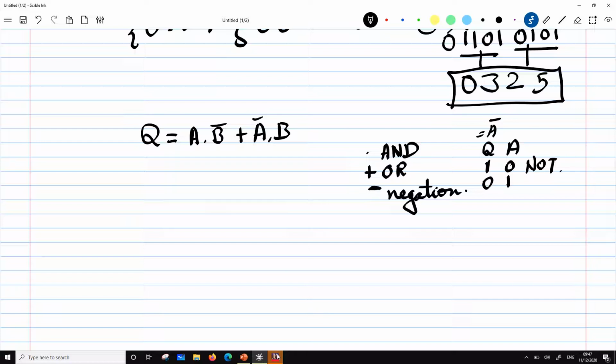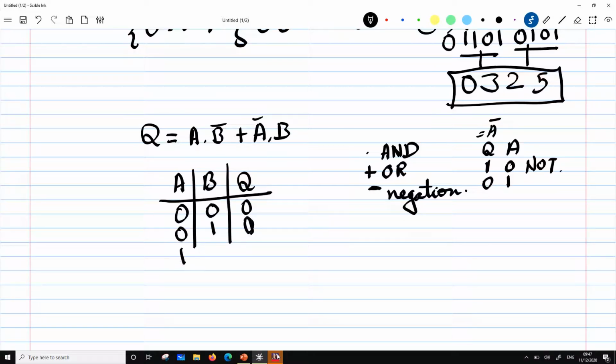Now besides the NOT gate, you have the AND gate and the OR gate. So what is an AND gate? I can write this as A B, and specify all the states here. If I put 0 0, then the answer is 0; 0 1 gives 0; 1 0 gives 0; and 1 1 gives 1. An AND gate is a gate where both the variables have to be 1 to result in an output of 1.